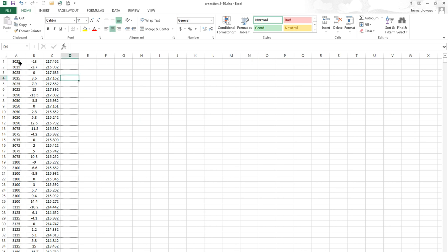We have the first column as the change, the second is the offset, and the last is what? The levels or the elevation. Now, some of them are negative, then there's zero, and others are positive. What do you think the negative one stands for? Yes, the offset on the left. Then what about zero? Yes, the ones on the center, and the positive are the ones on the right hand side. Very good. The last column is the elevations. You can also have a description, but for what we have, there are only 3 columns: change, offset, elevation.